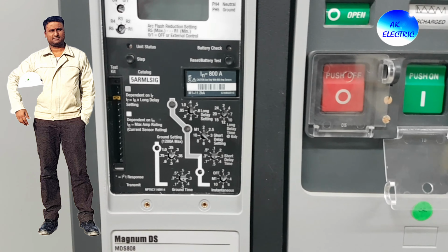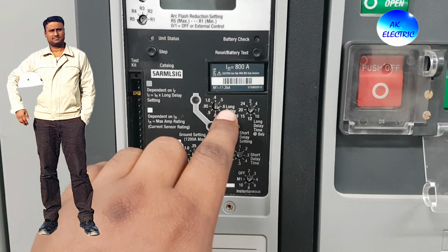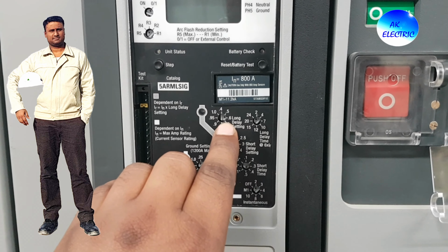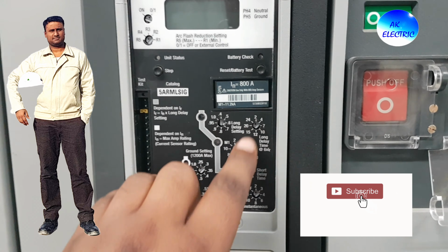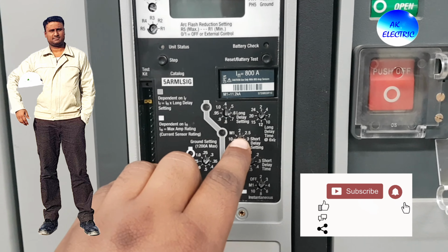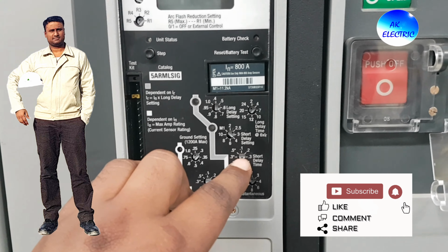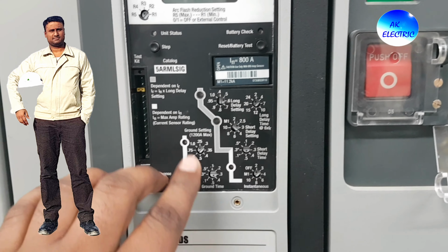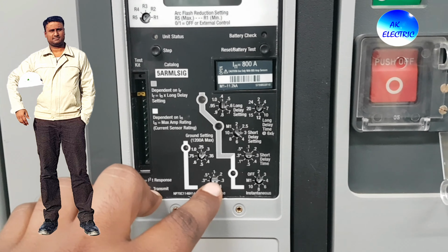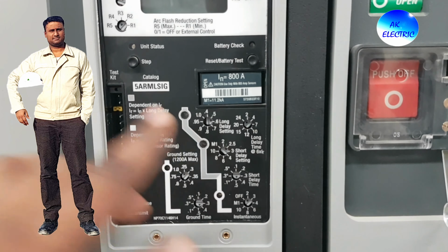Before going to the trip test, we have to see the long delay setting, and for that long delay setting we can set the time. For short delay we can set the time and the delay amperes, and this is the timing. This is for instantaneous, this is for ground fault, and this is the ground fault timing. For this we have to check the secondary injection trip test.